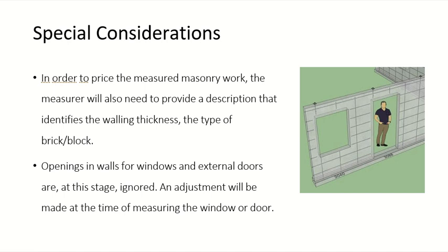Later on, once you calculate the walls and the doors and the windows, you will then subtract it from the total. Subtract it from the total. Like we did with the backfilling, you don't calculate the backfilling separately. You calculate excavation, you calculate concrete, and then you subtract and you find the backfilling. So same principle goes here.